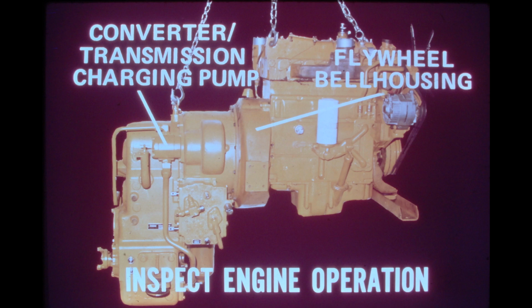This is possible because the charging pump is driven off the engine flywheel through the impeller. For this reason, engine operation and efficiency cannot be overlooked when diagnosing a torque converter transmission system problem.